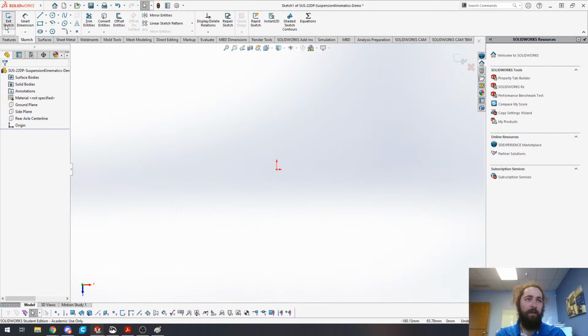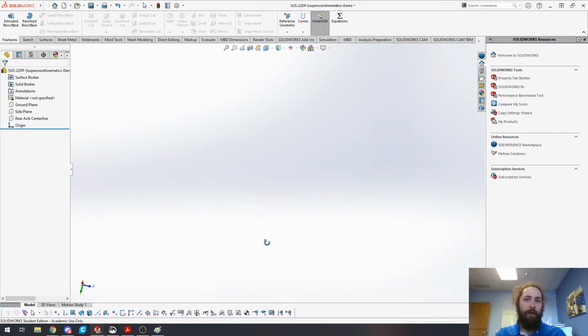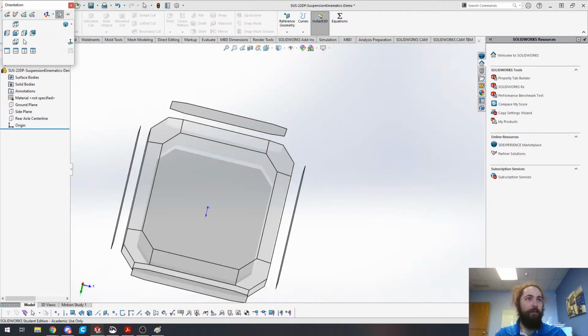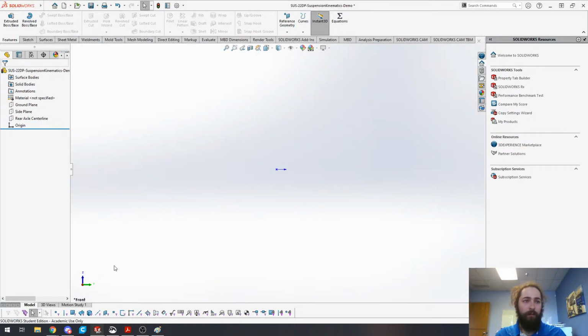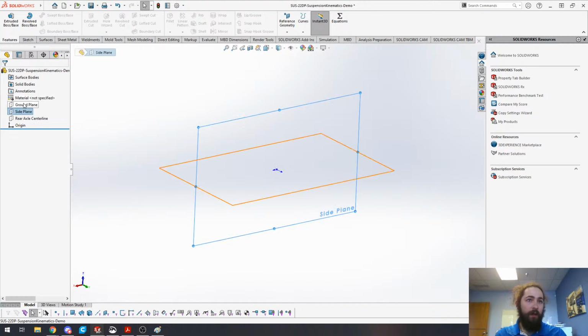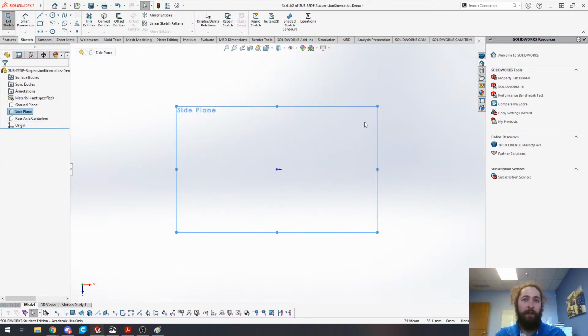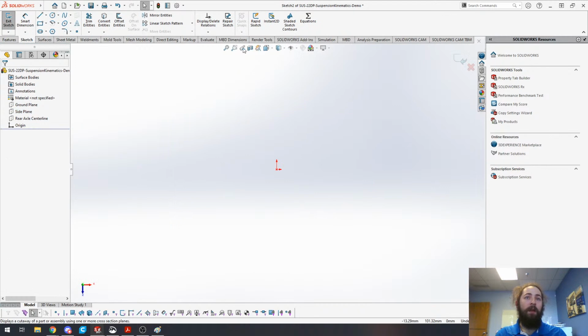And that's fun. Hold on. Okay, so there's our front view. For some reason, it decided that our z-axis is going to be pointing in a different direction now. Neat. So we'll just spin that around. Alt and arrow keys will spin stuff around for you, so you can see the z-axis is pointing up now. And we can go from here.